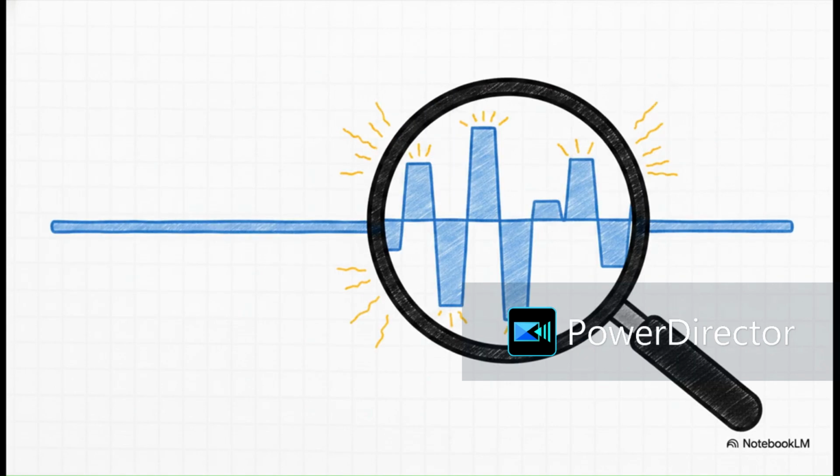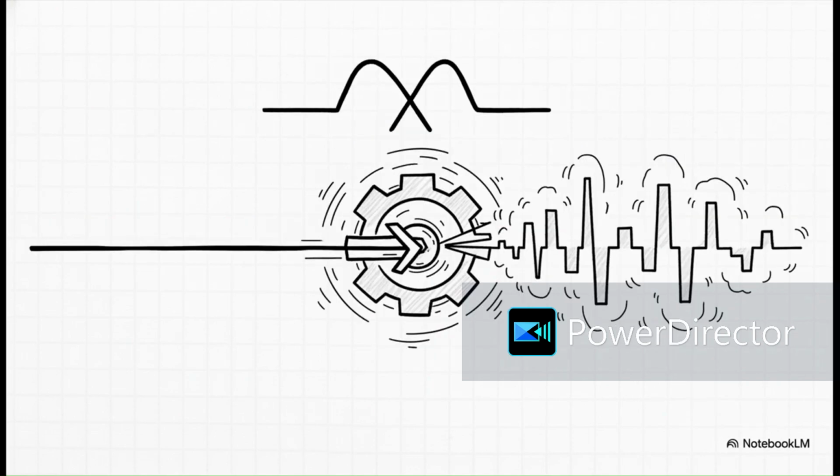Let's move in closer and see how this builds, because when you zoom in on the micro-reality, the entire illusion just breaks down. Those thousands of fast IGBT triggers mean the wave is actually made up of these rigid pulsed blocks. It's absolutely not a smooth line at all. It's just thousands of tiny continuous square pulses roughly stitched together. What you are seeing is the actual physical evidence of that switch snapping on and off thousands of times a second. And boom, right there is the answer to our missing sine wave mystery.